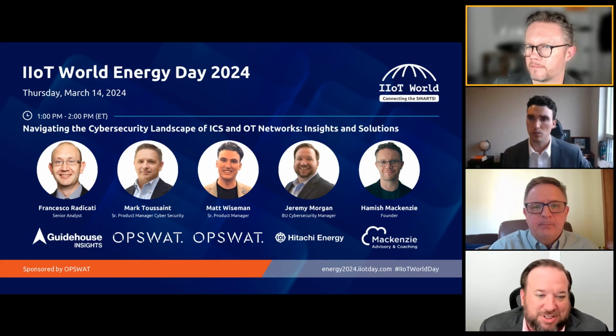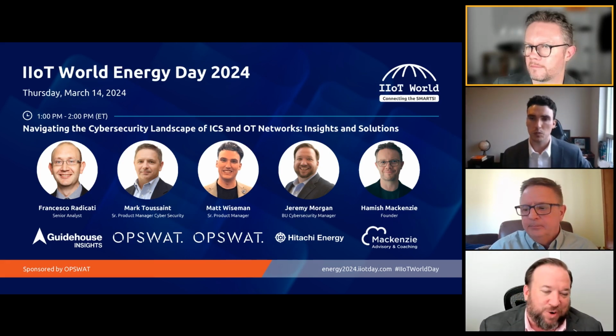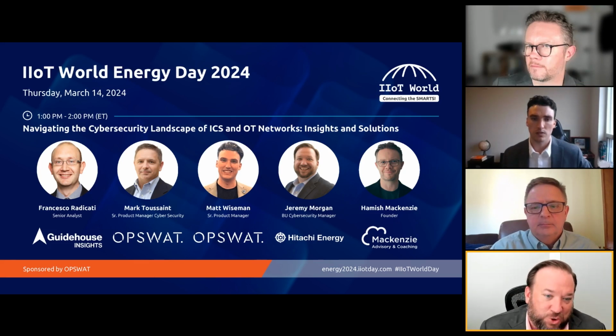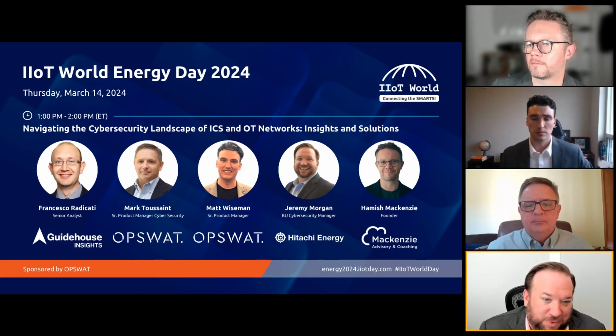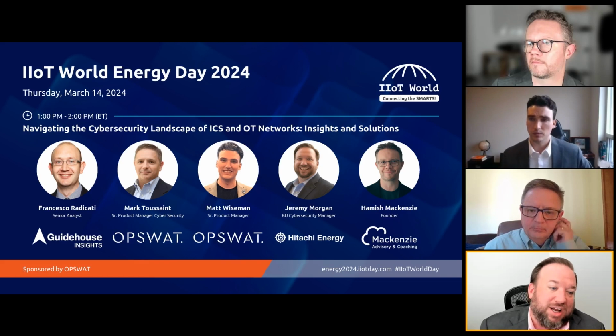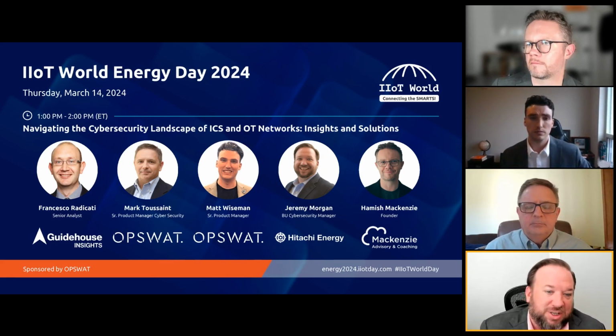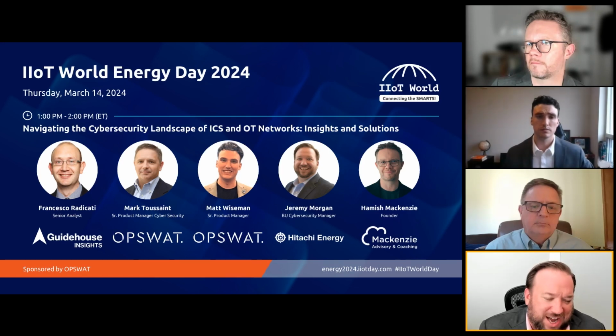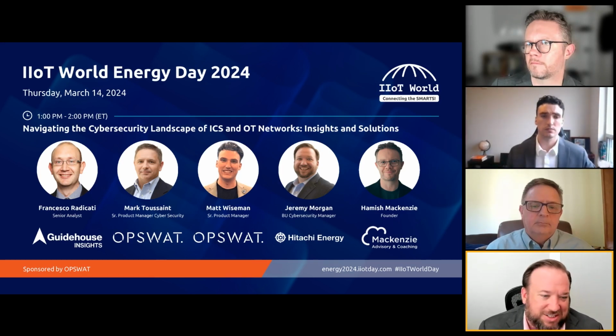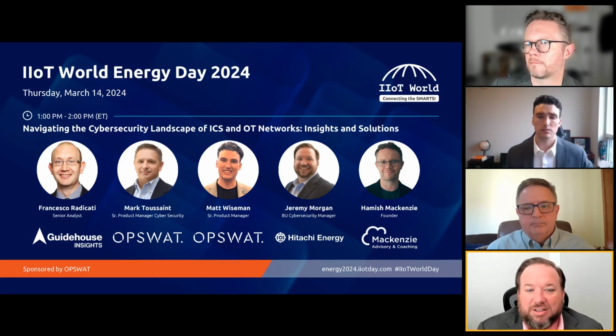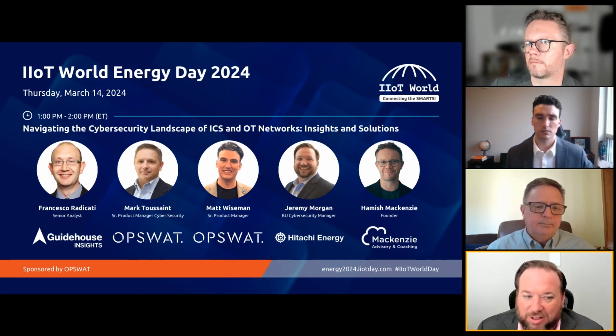I think it depends on what system you're talking about. If it's the core OT system, I'm going to be focused on 62443. If it's my edge systems that are pulling data out of my core OT system, 62443 doesn't have the greatest technology standards around internet connectivity and everything. And there, I would probably focus much more on the industrial internet security framework. There's a reason there's a couple.